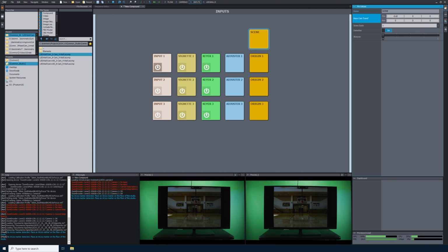As I mentioned in the setup of the custom Unreal Engine scene, you will always start at the world 0 of your level. So in order to move in the scene, you need to use these scene settings. If you watch preview 1 and 2, when I click and drag the Basecam transform position, this is updating the position that we're in the Unreal scene. This custom Unreal scene was built from World 0, but if your custom Unreal Engine scene wasn't built from World 0, you'll need to adjust these scene settings.